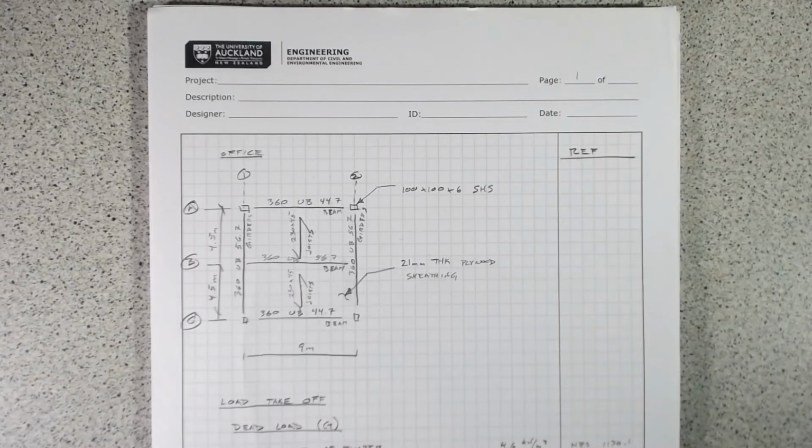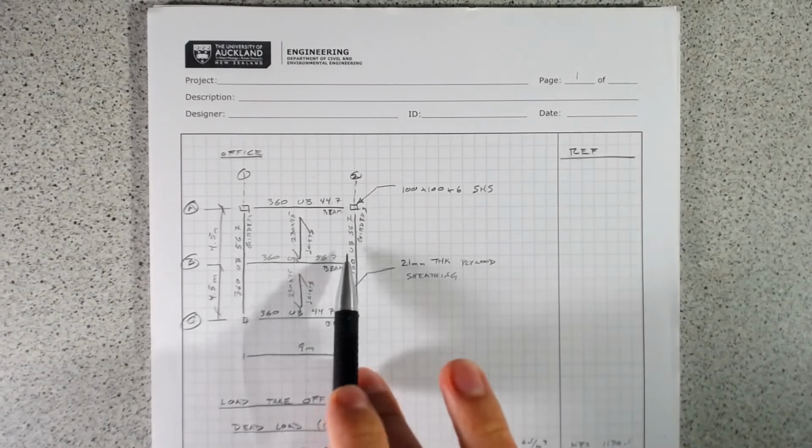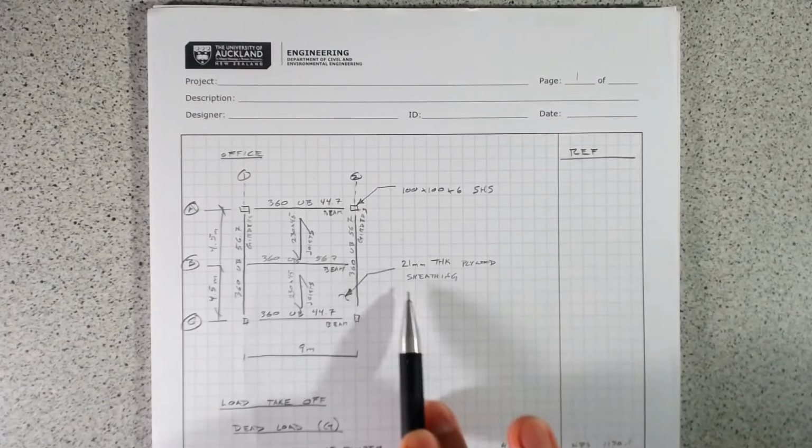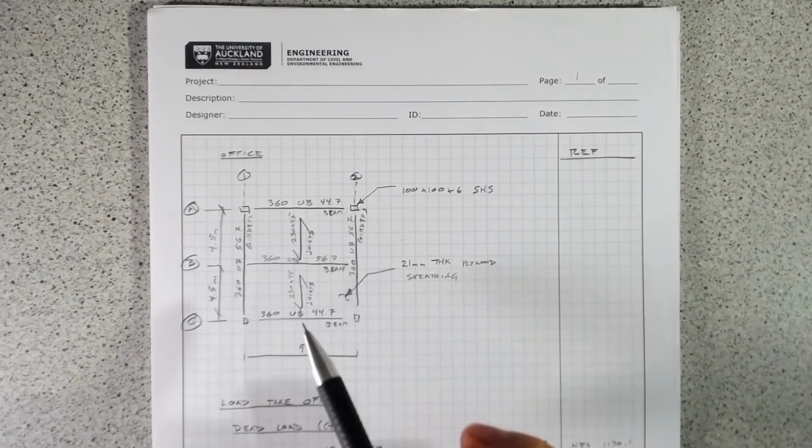So what we want to do is determine some loads on here, and I've gone through and done a load takeoff based upon the unit weights of the members. So with the steel members, what's useful is the second number here is the weight in kilograms per linear meter. But we're going to need to find out what the weights of the plywood and the timber joists are going to be so that we can then trace the loads all the way through the structure.